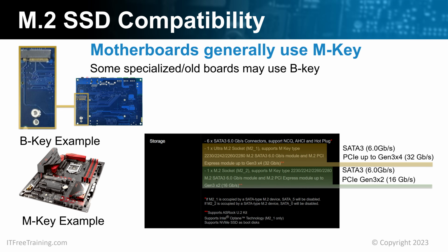The next thing to consider is that on this motherboard, if an M.2 connector is used, the onboard SATA port will be disabled. Essentially, what is happening is the wiring for the SATA port is being rerouted to the M.2 connection rather than the SATA port on the motherboard. This motherboard has 6 SATA ports, so hopefully that is enough. However, it is important to know so you do not attempt to plug in a SATA cable into a SATA port that has been disabled. Also, if you plug in an M.2 SSD and a SATA drive stops working, you will know that you need to unplug the SATA drive and plug it into a different SATA port.